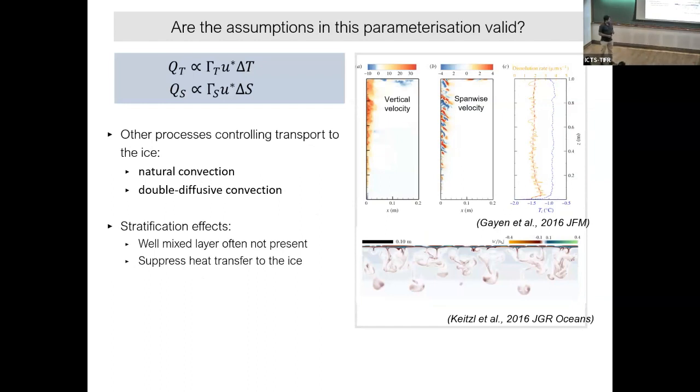Now, this is a very interesting point we came across: this drag coefficient and this transfer coefficient, those values are very old. Very old means this was done in 1960 or 1970, not even for the flow condition we have right now in Antarctica. We're running over a simple flat plate. Okay, flat plate simulation over a flow, and then you got the drag coefficient, and that has been used till now for all the models, anything you see. So there is a need to change, or a need to understand why we should use this drag coefficient. Okay, and is it realistic?